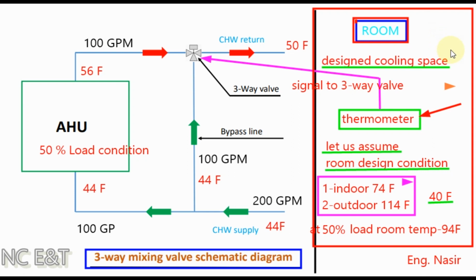The temperature inside the room will fall, and for our study let us assume the indoor temperature became 94 degrees Fahrenheit, that is, the load became 50% of the design load. This indoor temperature will be sensed by the thermometer and it will give the signal to the three-way valve, and